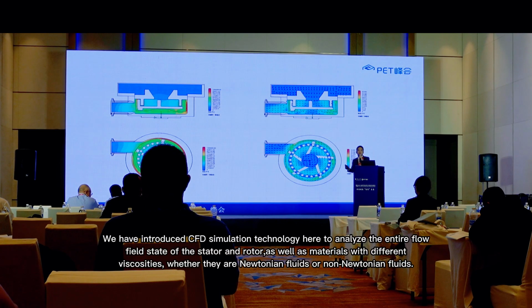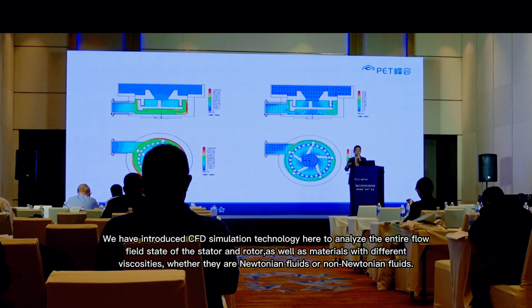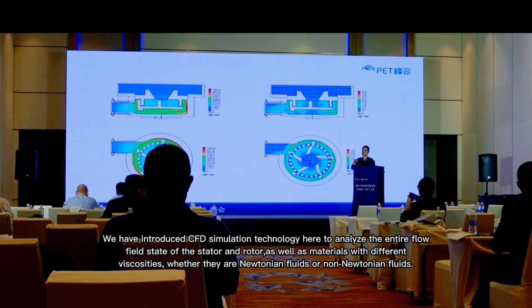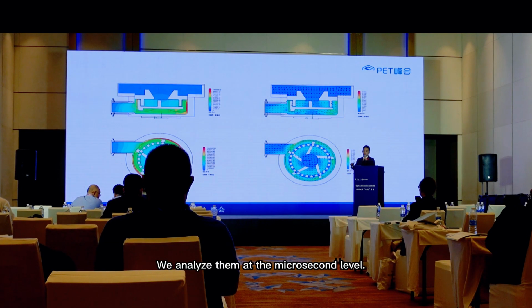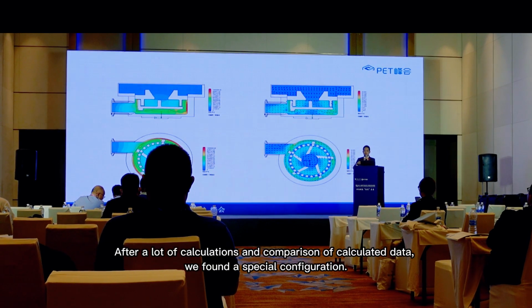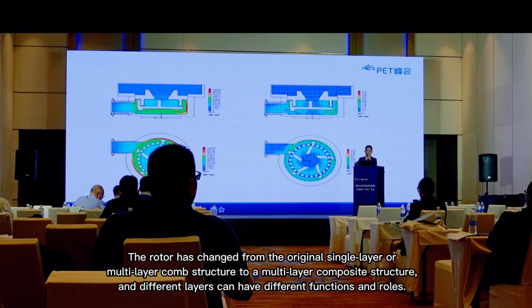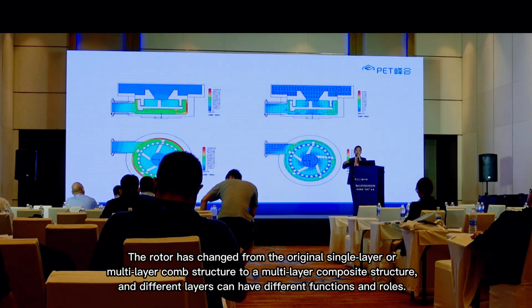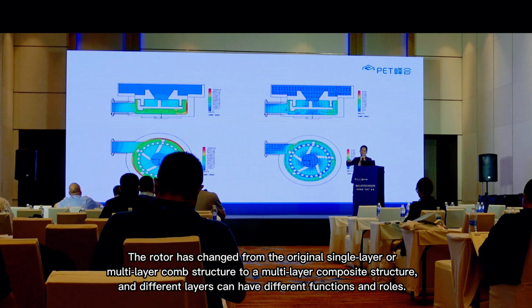We have introduced CFD simulation technology here to analyze the entire flow field state of the stator and rotor, as well as materials with different viscosities, whether they are Newtonian fluids or non-Newtonian fluids. We analyze them at the microsecond level. After a lot of calculations and comparison of calculated data, we found a special rotor, which has changed from the original single-layer or multi-layer comb structure to a multi-layer composite structure, and different layers can have different functions and roles.